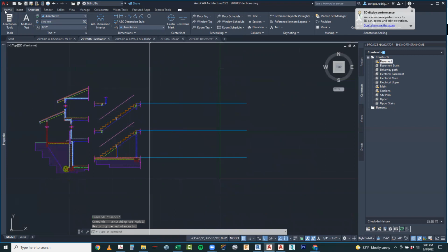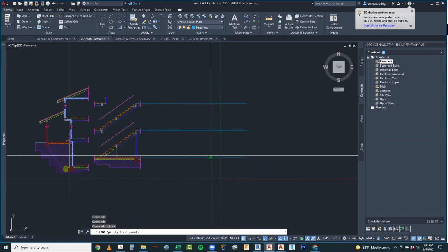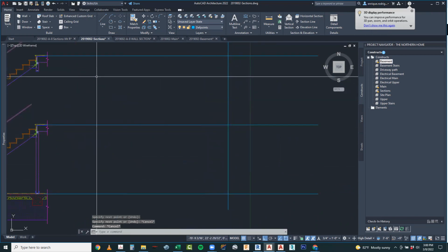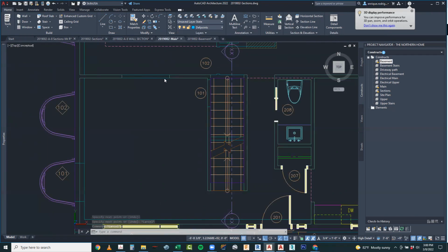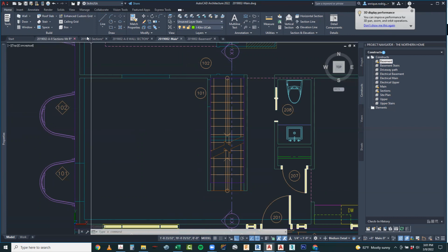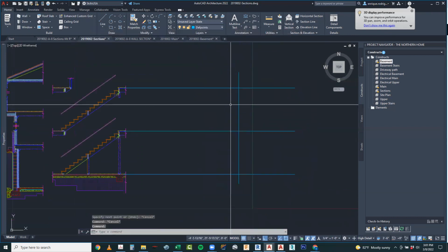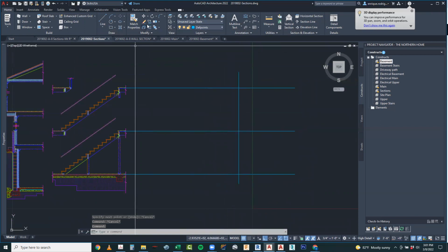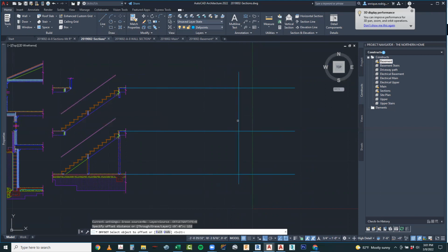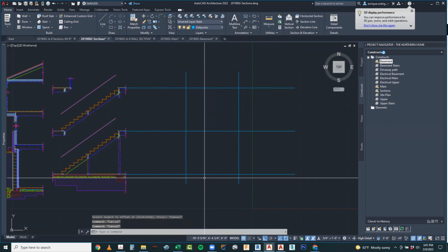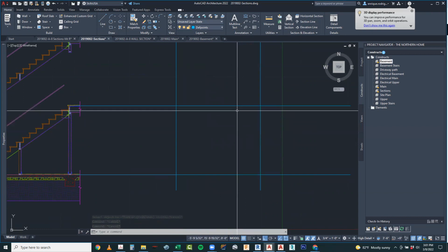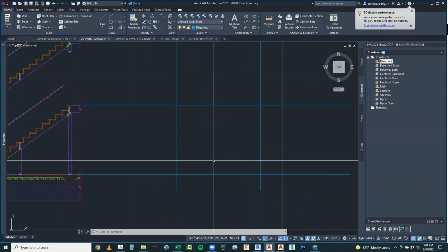And I'm going to draw a line. And again, I'm still in def points because these are just guidelines. That's going to represent the inside face of my wall right here. Let's go back to the sections, and I'm going to offset this 132 inches. And so right inside of this rectangle, 9 feet high by 11 foot 10 inches, I'm going to do my